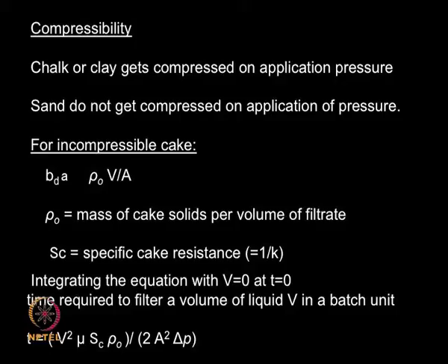sometimes the bed itself can offer resistance if we increase the pressure of the filtration process. So if the bed resistance increases as we keep on applying an external pressure, then it is called a compressible solid. That means as we keep increasing the pressure, the bed gets more compacted, so that is called a compressible solid.